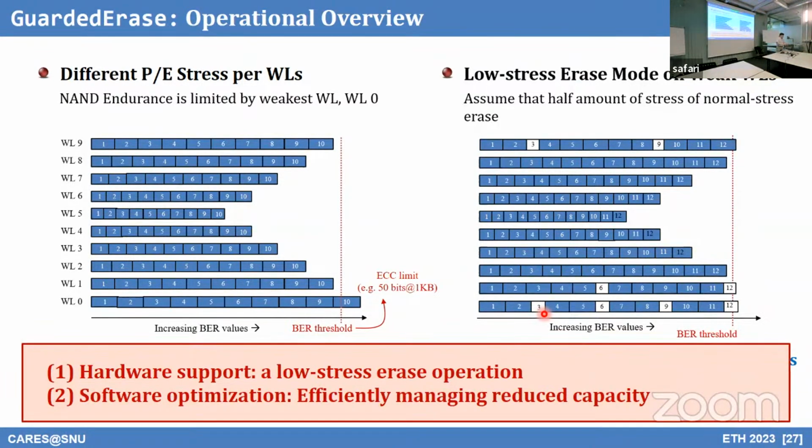Yeah. I'm not fully aware of low stress mode erase. Does it still keep some electrons in the charge trap? You write data to the word line, and then you erase the whole block. Then you can write other data to the same word line. That's the normal erase mode. Exactly. But low stress erase mode...